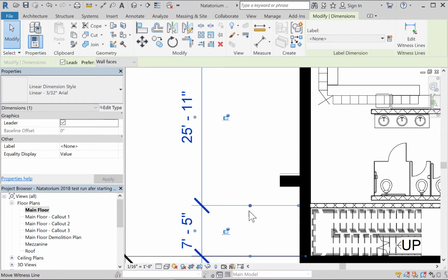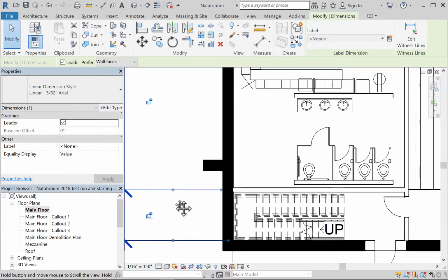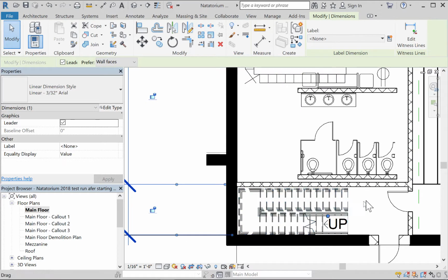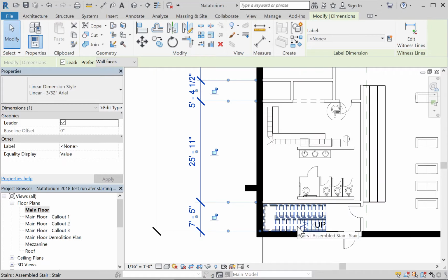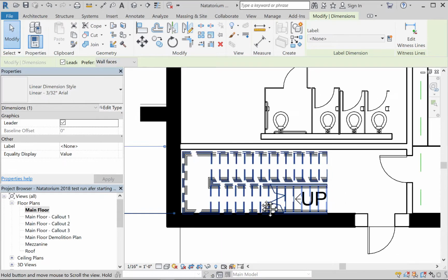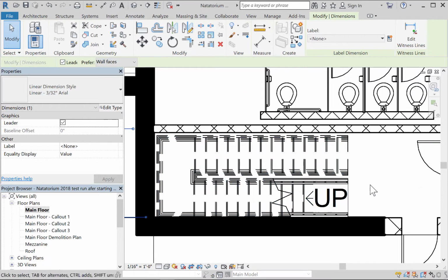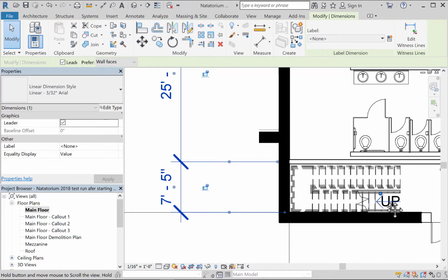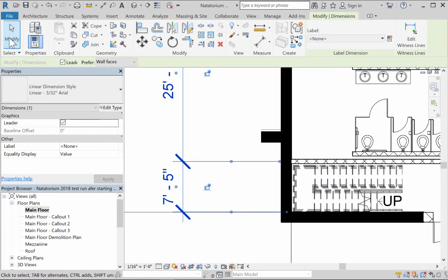Okay. If you don't remember, with Revit dimensions, you can click and drag on the grips to kind of control where they are. Okay. What I will sometimes do, we are not going to do a stair drawing, probably, unless we get lucky and have a lot of time. In a stair drawing, obviously, just like a toilet room, clearances are absolutely critical. So I would almost certainly do a much larger blow up of this stair area, in which case, don't provide dimensions in that area. Okay.